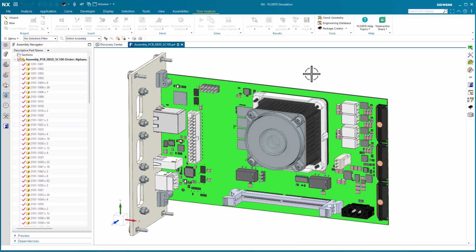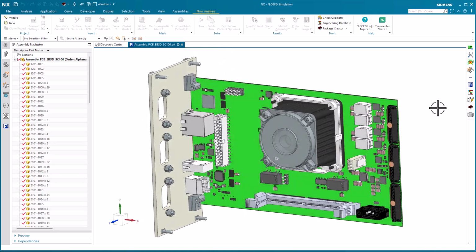One of the most common questions in electronics thermal analysis is how to model heat generating components. Datasheets give some insight on performance, but often a lot of assumptions need to be made, and as the junction temperature is the most critical value for electronics analysis, it's crucial to get component modeling right. This is where IC thermal model calibration comes in.